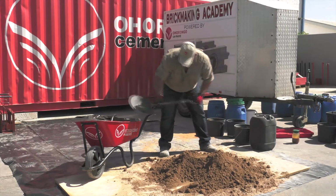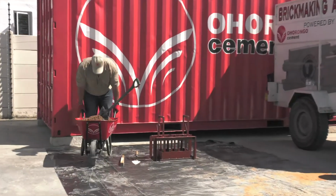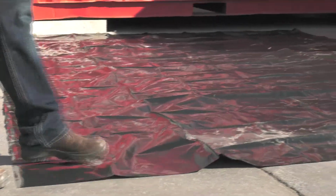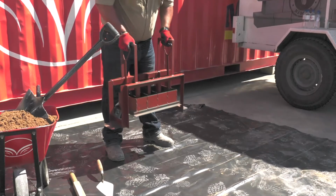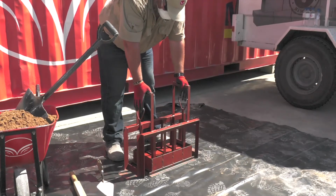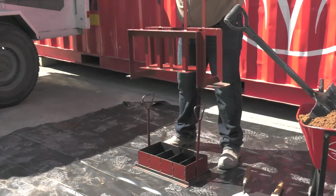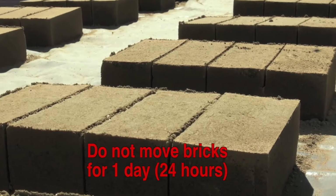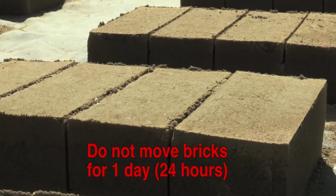Place the concrete mixture in a wheelbarrow and take it to the second area where you are going to mold the bricks. If you have plastic sheeting, place it on the even surface where you're going to mold the bricks. Place the brick mold on top of the plastic sheeting or the shutterboard at the place where you want to mold your first bricks. Remove the top section of the brick mold so that you can fill the bottom part with the concrete mixture. Keep in consideration that the bricks need to remain in this space until the next day before they can be moved.